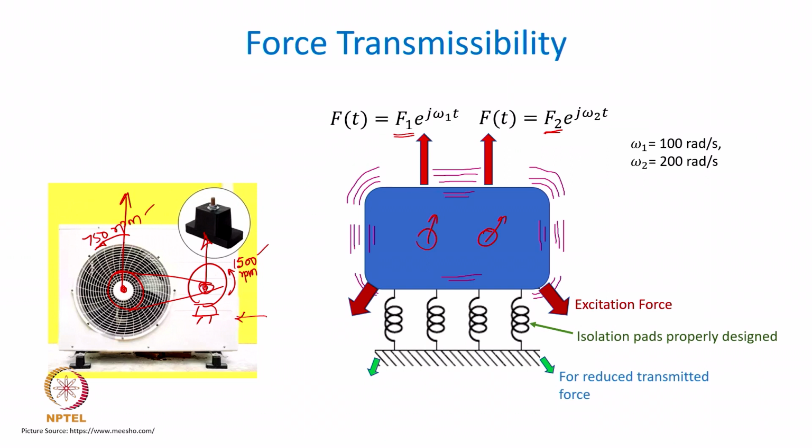Okay. How do we do that? We have just seen in the previous slide that we properly evaluate the value of k as well as c. Now, we have seen how k is important. k is important for influencing an appropriate natural frequency, but that natural frequency depends upon what omega is. Omega n is decided or designed to have a certain value depending upon what omega is, which, for a given fixed mass, will only influence what is the value of k.